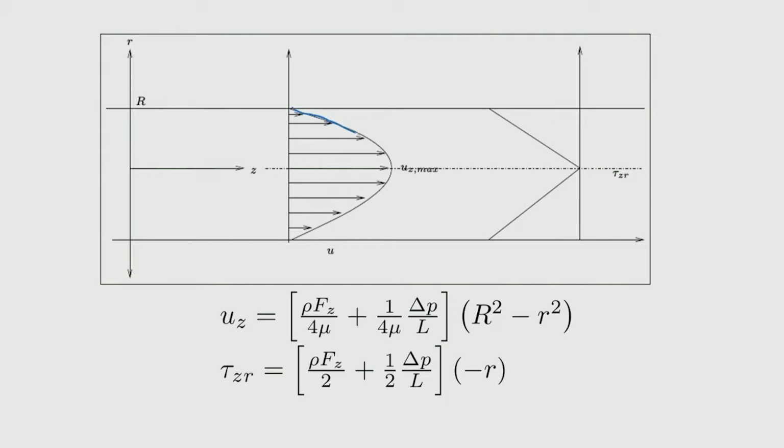Now, when we plot this parabola, it would look like here. So, this is the plot we are trying to show. Which means that in the tube at the center is the maximum velocity, and at the walls it is 0 velocity, and the slope at the center will be 0, and the parabolic is the nature of the velocity as a function of r in the tube.